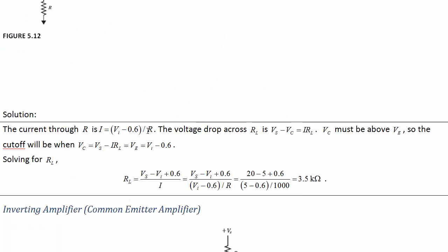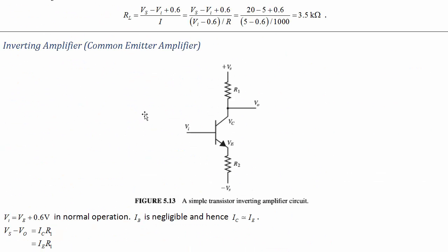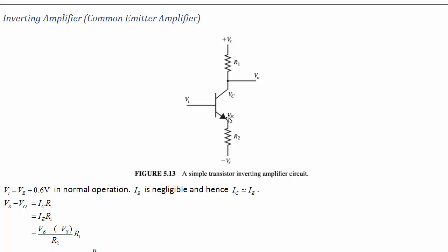Now, another way to look at this exact same circuit is as an amplifier. Let's see why it could be an amplifier if we adjust the resistance values appropriately. Because the collector current, which is basically the emitter current as well, is much larger than the base current, we can adjust this voltage a little bit to get a big change in the current, and that might change the voltage if we set our resistor values right.